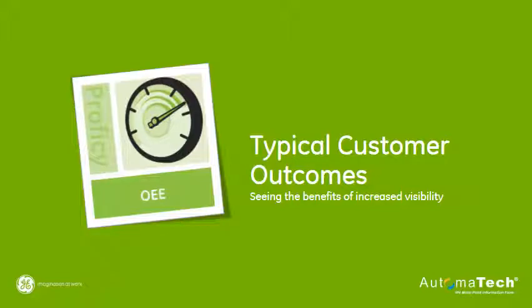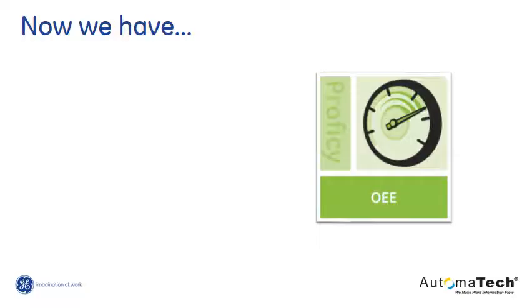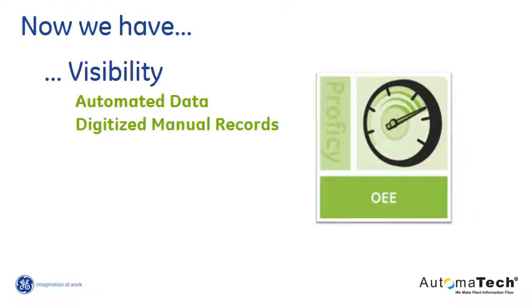Let's turn now to some typical outcomes that customers have seen just by utilizing an OEE package. So let's review what we do get with a fully implemented OEE system. The big focus, again, is on automated data. That means the machine is telling us when it's going down, when it's kicking off waste, and how fast it's running its production versus its ideal rate. So the information is much more accurate, and we can start pulling analytics out of it and also alerting people when things happen to be going wrong in real time.